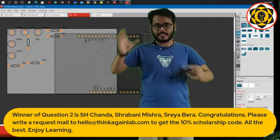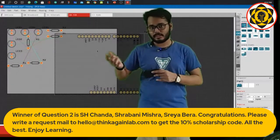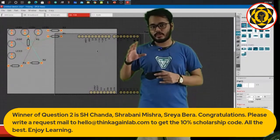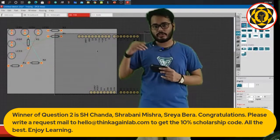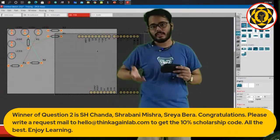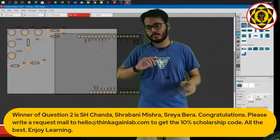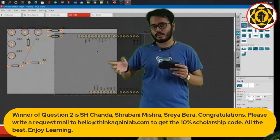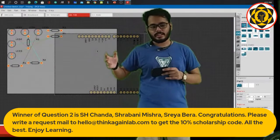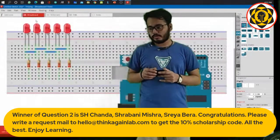So it's very good if you're making a simple design, or if you are a beginner. That's why I would recommend selecting a model that corresponds to the Arduino you're going to be using in actual life. Then you can just drag and drop and place it on the Arduino. We are going to be using an Uno because that's very beginner friendly. So I have selected an Uno, and this has concurrently loaded a Uno blank right here. So let's go to the breadboard view and connect the stuff.